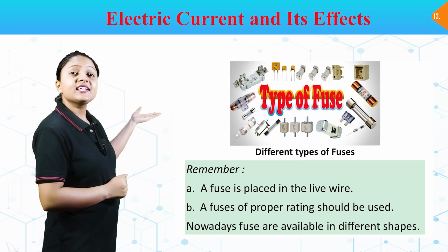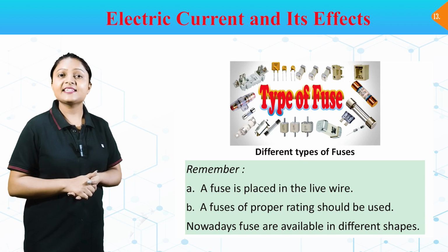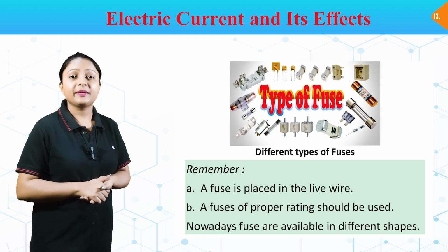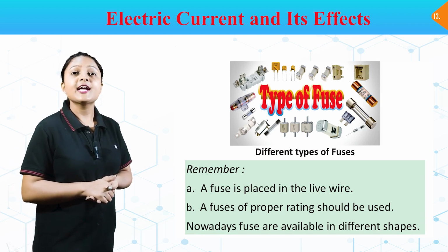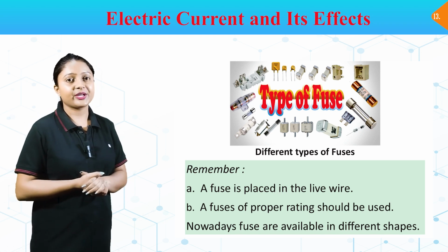In this image, you can see different types of fuse. Remember, A. A fuse is placed in the live wire. B. A fuse of proper rating should be used. Nowadays, fuses are available in different shapes.